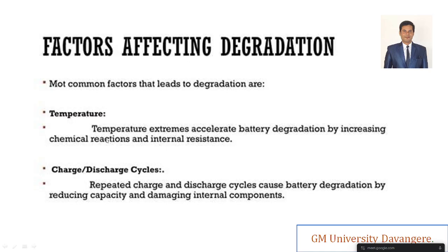If you overcharge, what will happen? The temperature will also rise. Yes or not? So the same thing, because this is one of the factors for degradation. You cannot have overcharge. If you charge your battery for very long times, without unplugging your battery from the supply, what will happen? It gets overcharged. So during that time the battery may also degrade its life because of the rise in temperature. So temperature extremes accelerate the battery's degradation. Temperature is a major factor.